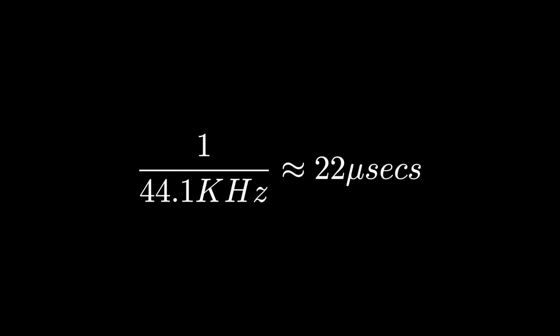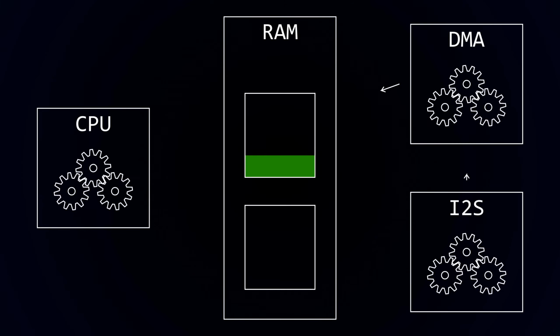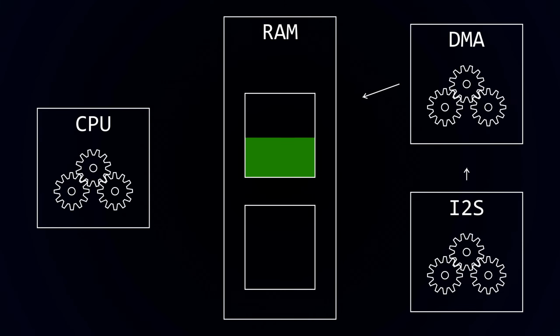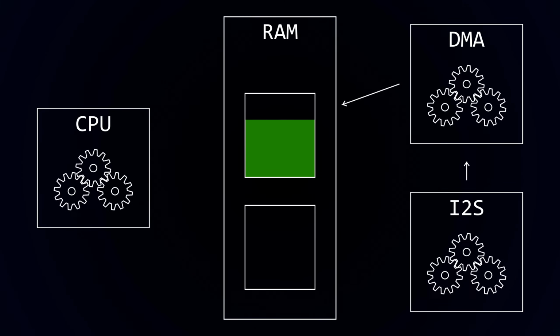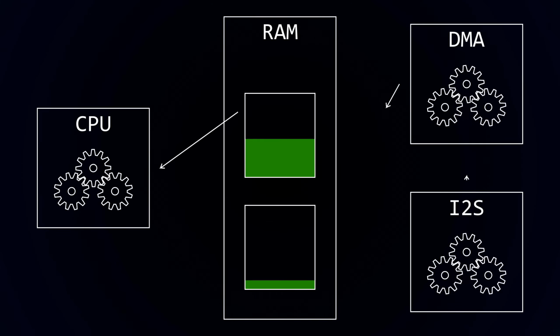With a sample rate of 44.1 kHz, we only have 22 microseconds before the next sample comes from the device. This is not very long. It's unlikely we could do anything meaningful in this time. Our processing task may not even be scheduled quickly enough to even catch the data. The result of this means that you typically want to set the DMA buff count to at least 2. With 2 buffers, you could be processing one buffer with the CPU, while the other buffer is being filled by the DMA controller.